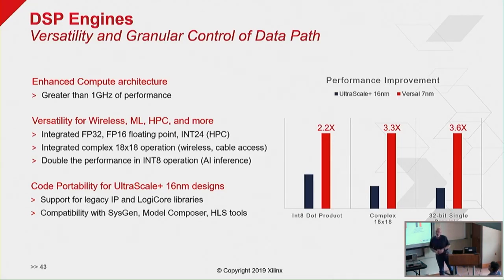So what is the difference between the Versal DSP engines compared to the normal DSP 48 that is in the FPGA 5? It's been quite intensively overhauled, so we refer to it now as DSP 58, for example. It's wider. It's got a lot of new functions in there. It would be hard for me to remember them all, but you can do expression matching up to like 118 bits and a whole variety of other things. So it's been extended dramatically, and it's like a superset of what you saw before. That's still in the FPGA fabric. Yes, not like software. It's still in the FPGA fabric.